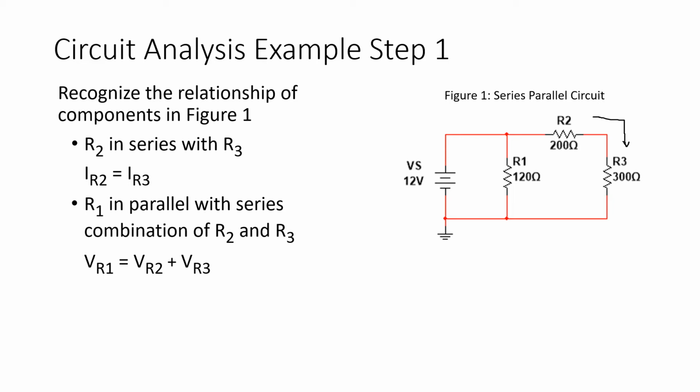So we can state that VR1 equals VR2 plus VR3. And also, I hope you can recognize the fact that resistor R1 is in parallel with the source voltage. So we can also state that VS equals VR1.